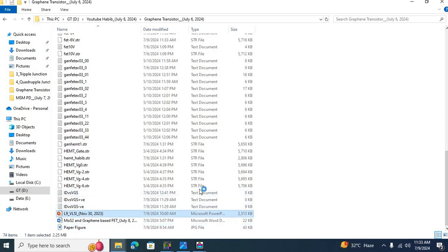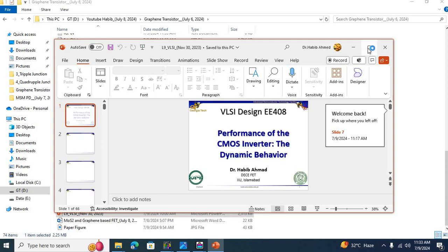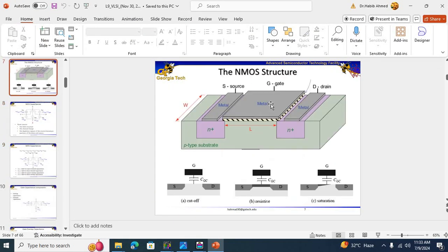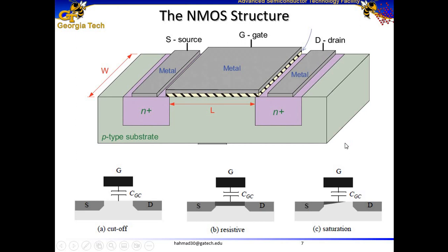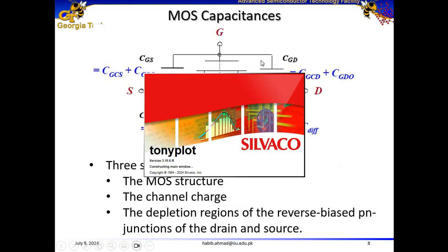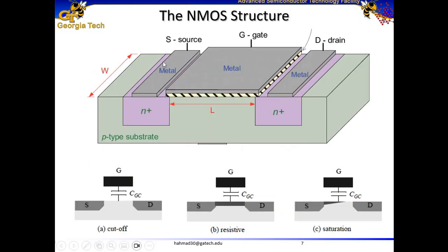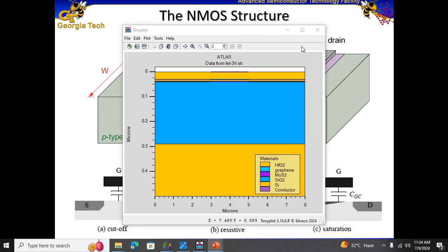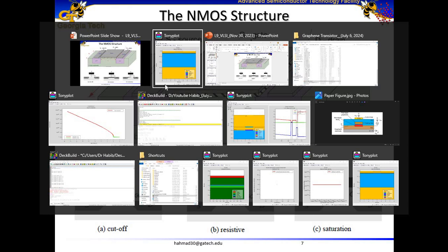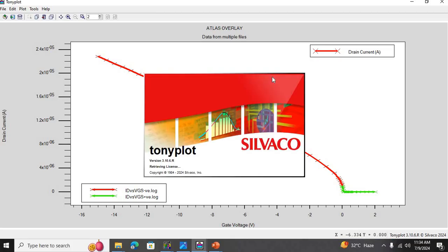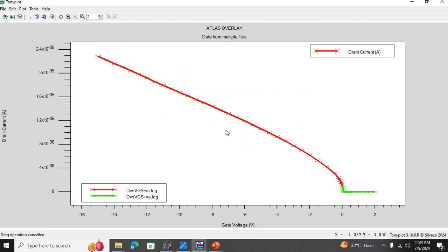So, for example, if we talk about the conventional silicon based field effect transistor, this one over here, we know that for the conventional n-type MOSFET, we need to apply a positive gate voltage in order to attract electrons from the bulk region towards the channel, towards the surface, in order to form the channel. So positive gate voltages would actually form the channel and turn on the transistor. However, in this scenario over here, we see that it's going to be the negative gate voltages which are going to turn on the transistor, the molybdenum sulfide based transistor.